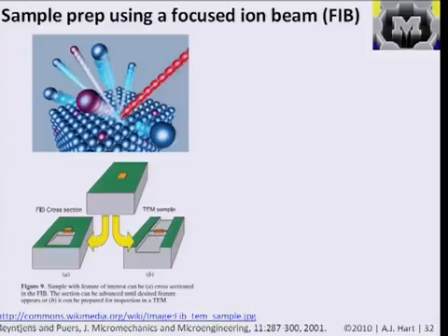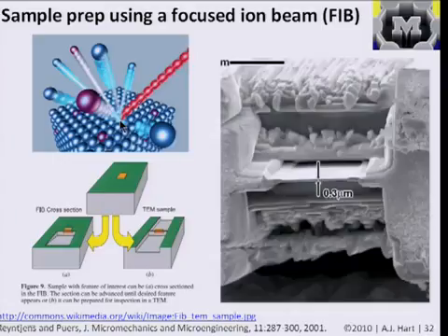All these atoms also result in junk, so you get some small scale junk in the process as well. And here's a picture of a sample that was actually a multi-layer circuit structure machined by FIB, basically cut out to reveal this thin 300 nanometer section, which was then put in the TEM and had an image taken.